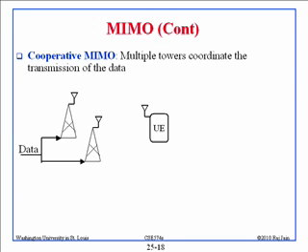All right. Then there is what is called cooperative MIMO. Cooperative MIMO is doing the same thing, but on the tower side. Instead of having 1 tower with 2 antennas, which is much easier to do, it's no big deal to put an umbrella on a tower, if you use 2 towers to transmit, then you have cooperative MIMO. These 2 towers are collaborating to reach you. Right? So this is another kind of MIMO. All of these modes are allowed in LTE.